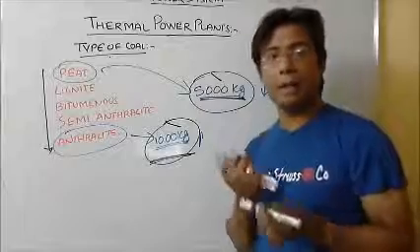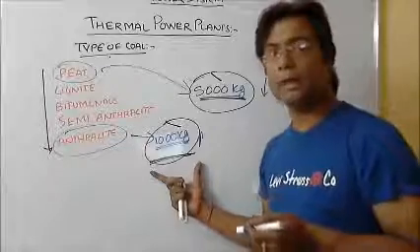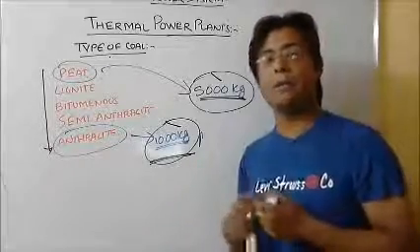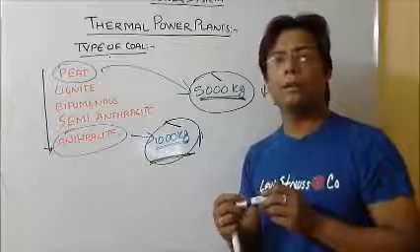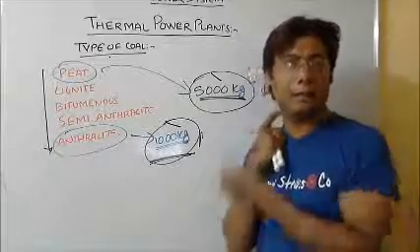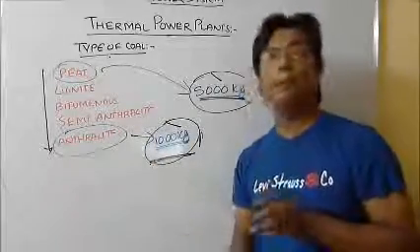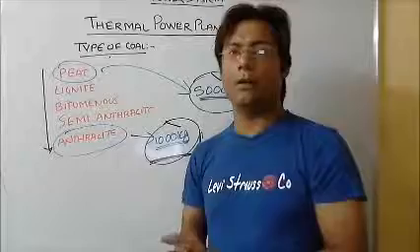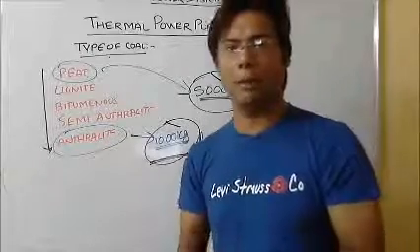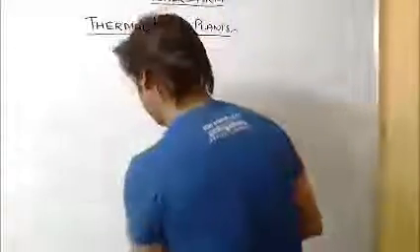So the ash handling plant has to work more in the case of peat, and in the case of anthracite it will be working less. In the same way, ash storage will be very high. The ash handling plant has to work at a high capacity because ash handling would be much more difficult in the case of peat, and in the case of anthracite it will be low. So one can now understand how the transportation of the coal increases or decreases the efficiency of the total thermal power plant. One more thing comes in here, which is the type of the boilers.